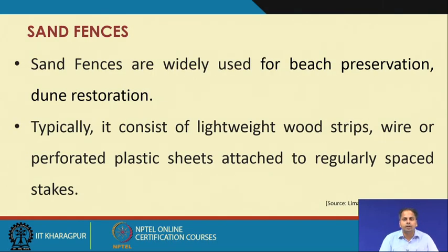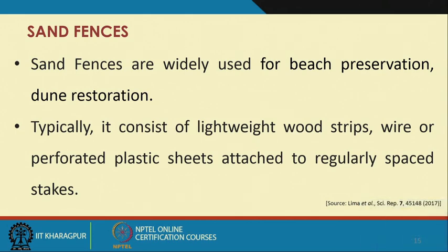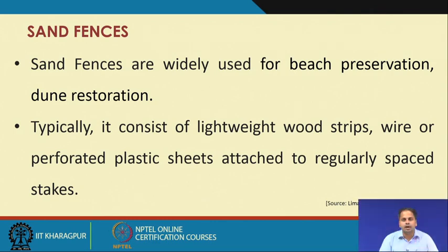Then the most common and most popular temporary measure to control the sand movement is the sand fences, or construction of sand barriers in the form of benches. The idea is that they trap the sand and stop further movement of sand, or they can stabilize the sand dune, or form artificial sand dunes, so that further movement of sand in the inward direction can be stopped.